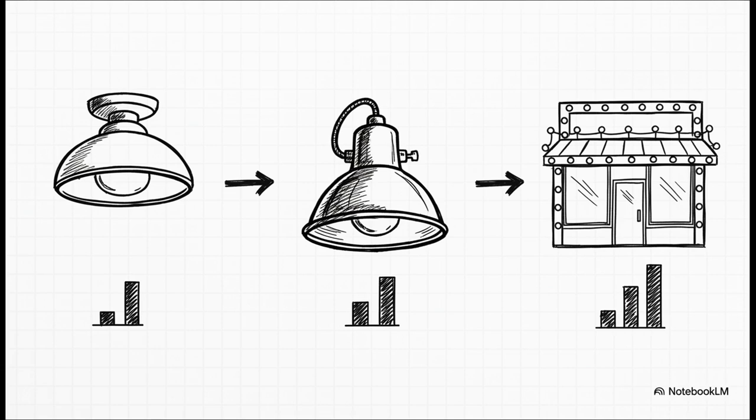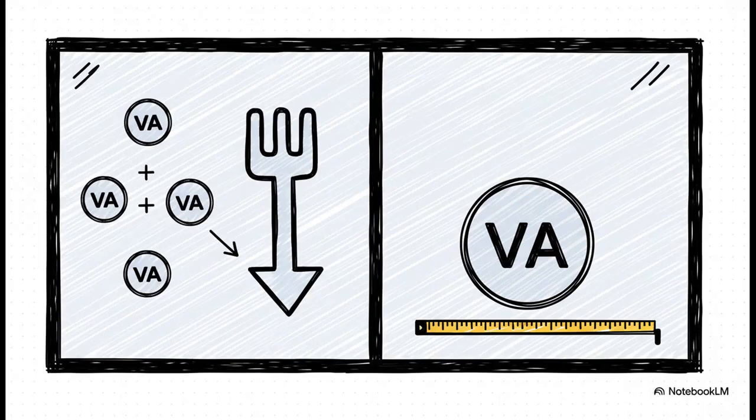For those really big, heavy-duty lamp holders, you have to assign a minimum of 600 VA. And for things like commercial signs and outline lighting, that load jumps up to a minimum of 1,200 VA for each branch circuit that's required. But here's where things get kind of interesting.